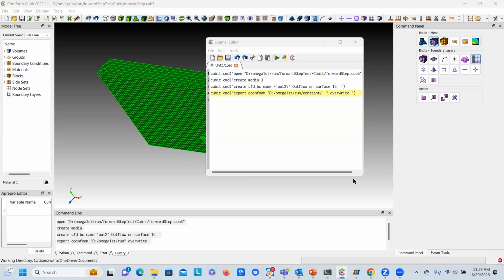And I see that there's another question out there about the native mesh importer, like a fluent.mesh file. And what I would say there is that one of the nice things about Cubit is that it allows you to create natively the mesh file for OpenFoam. So if you're converting from a Fluent mesh, generally you have to have Fluent or something on that order on the machine. And so you've got a few different ways of going about doing that.